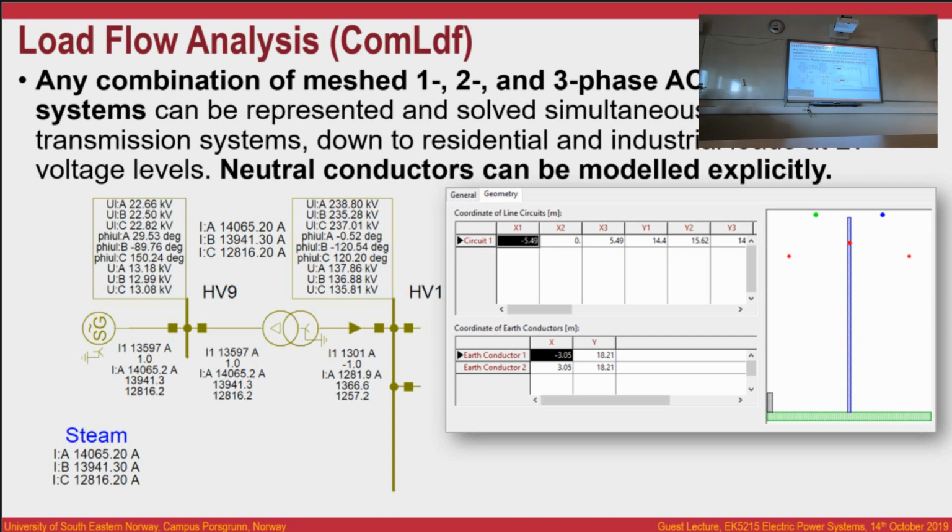And one characteristic of the transmission system is that they are three-phase, and also they have very, very low resistance and a bit high reactance. However, sometimes we have distribution systems. In distribution systems, the history is a bit different because you can have 2 phases, 1 phase, or 3-phase system, all of them combined. And they create something called asymmetry. That means current and voltages can be different.